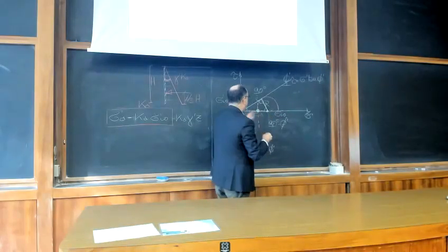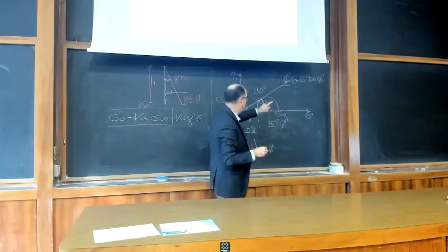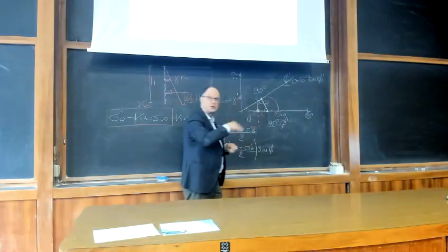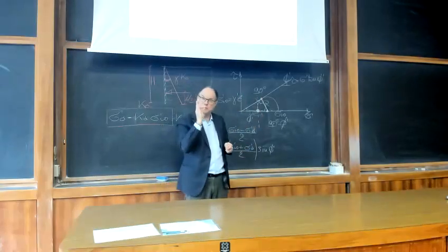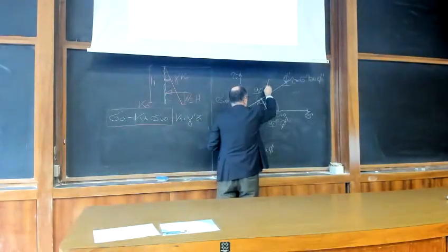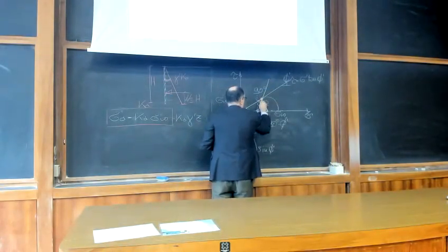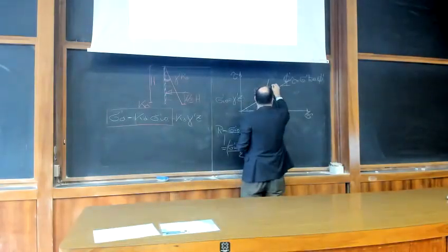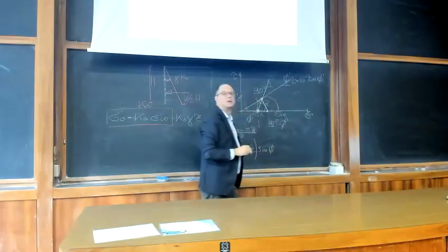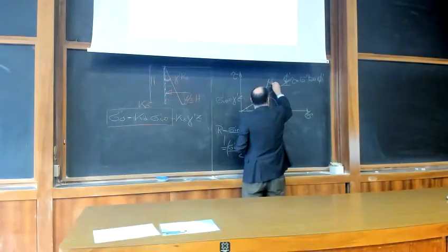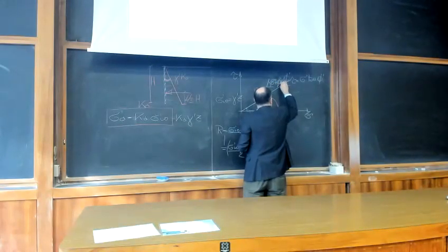So the failure plane, where you reach failure in these conditions, is represented by this point. Remember, in the Mohr circle, each point represents a specific plane. So if you connect this failure point with the origin of planes, then you find the angle of your plane. And this angle is exactly 45 degrees plus phi dash divided by 2.